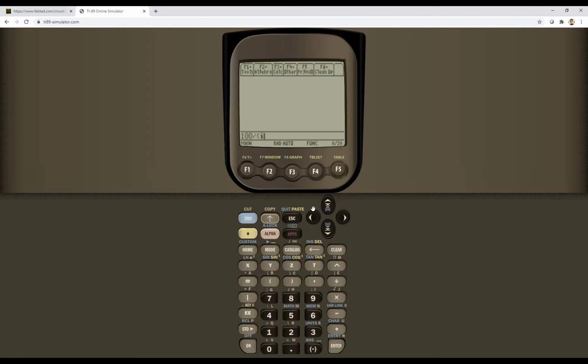And then times 377, times 100 times 10 microfarads. I can go 10 e to the minus 6, plus 1. Okay, enter. Look at that. 87.56 and minus 33j. It spits it out for you in rectangular form.